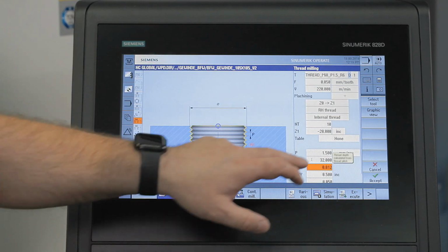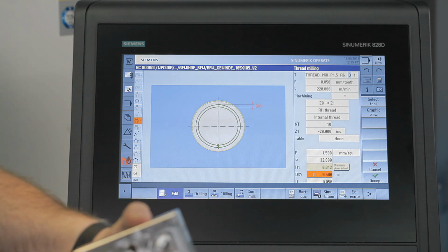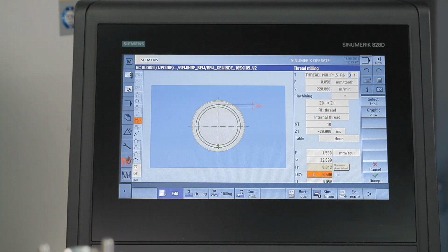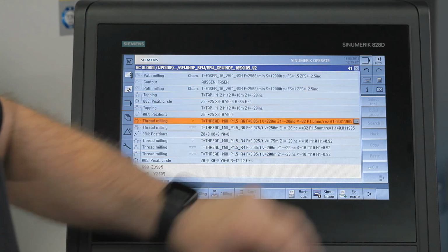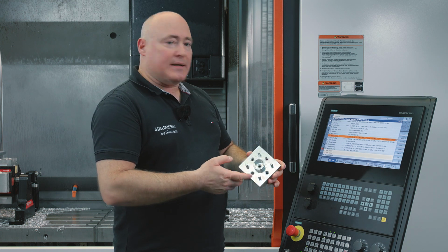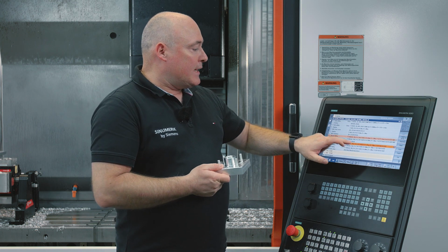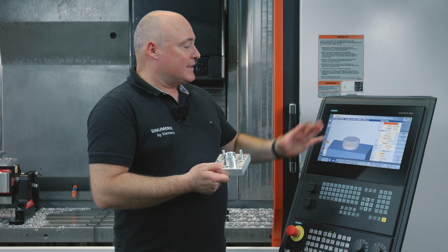This concludes the setting of all values. H1, for example, is the flank height of the threaded tips, which is calculated automatically and entirely independently by the system for technological reasons. As is the case for the large thread, it is totally irrelevant for the cycle whether a large thread or a small thread is involved.